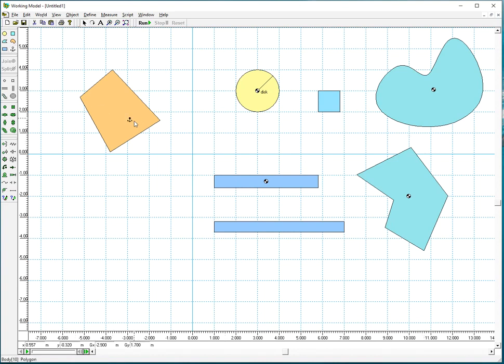So I snap it, and I have the body immobilized relative to the background, the ground link. This can also be achieved with the rigid joint, which locks two bodies together. So I'm locking the background with this polygonal body, or I could lock these two links together. Okay, by default this is the vertical plane.